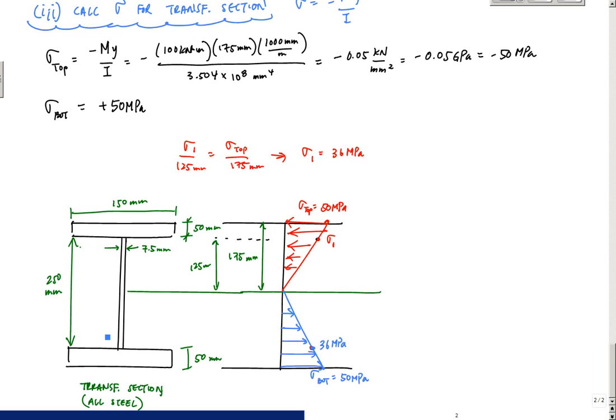To draw the strain profile, I just had to divide every single number here by the modulus of elasticity of steel. Let me call this step 4, strain profile.